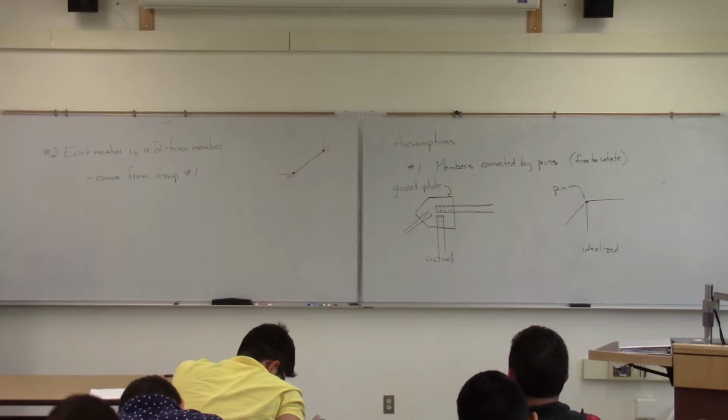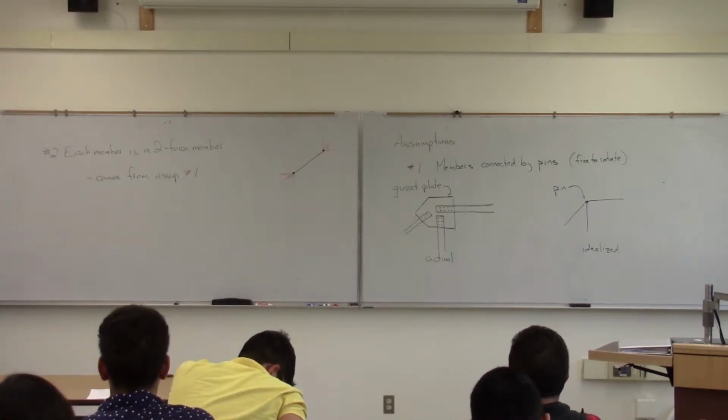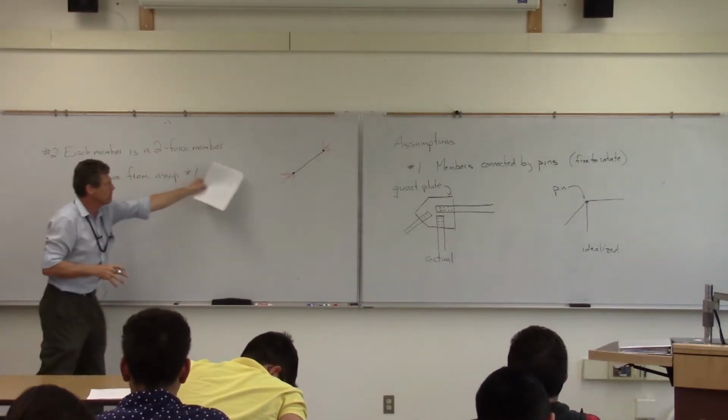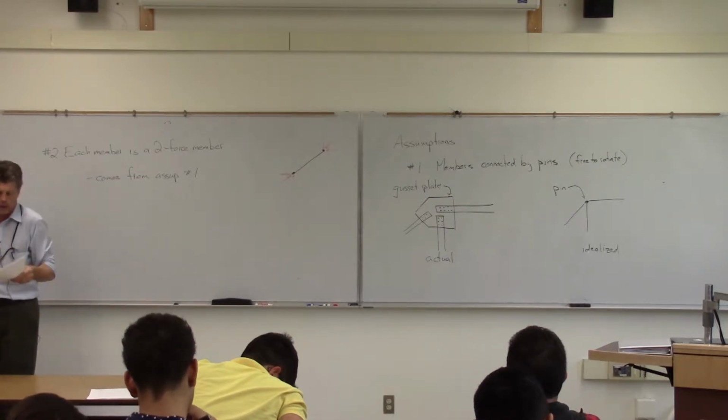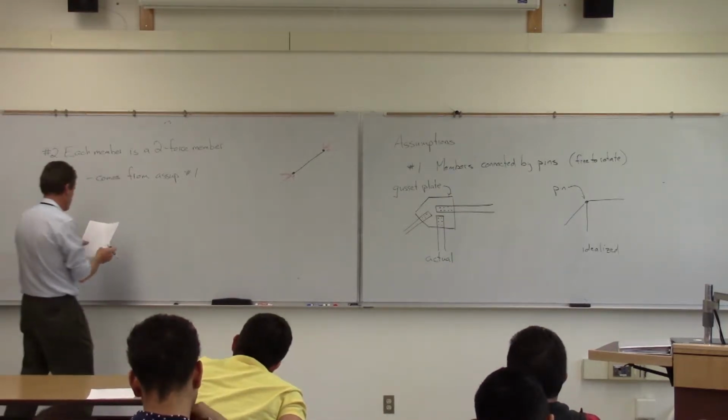Basically, now that we've assumed that those ends are pins, we can state that those members are going to be 2-force members.